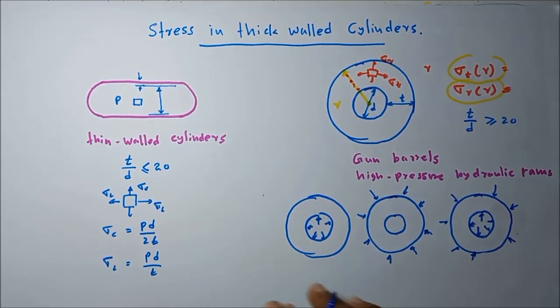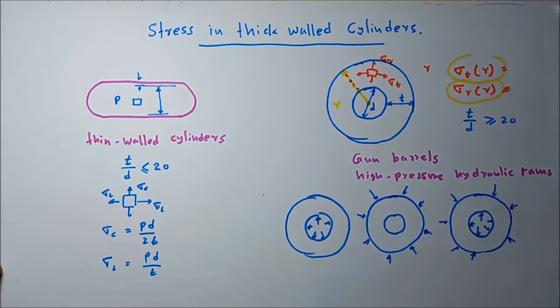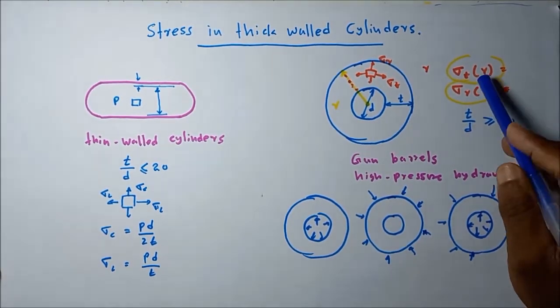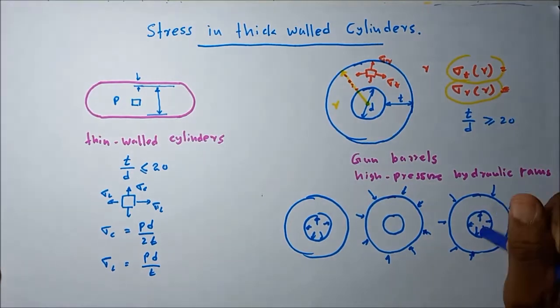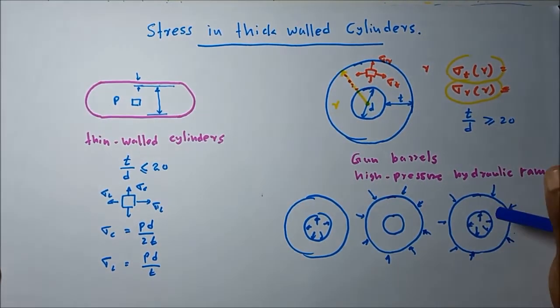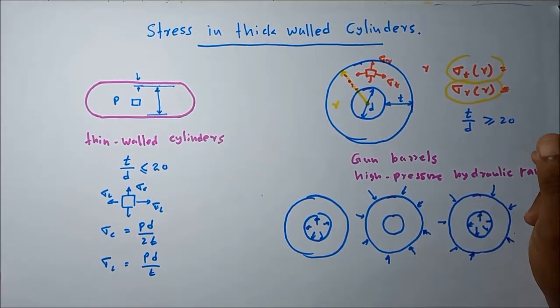Okay, the various applications include shrink fittings. We are also discussing the shrink fitting related to these thick wall cylinders. First of all we are going to obtain the equations for sigma t and sigma r considering the general situation, the cylinder under internal and external pressure both.